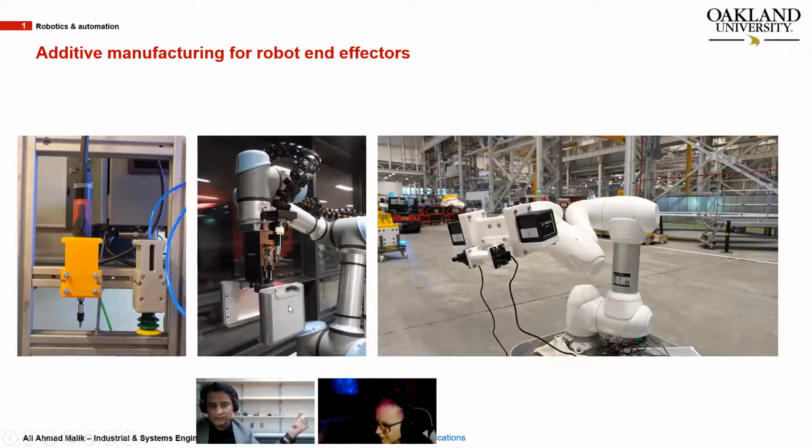For example, here it is attached to a gripper, or these tools are also developed with 3D printing and the robot can pick them with its fingers. In the case of this robot, it needed to pick or hold some lasers, so this whole component is developed with 3D printing. If we had tried to develop this by machining out of aluminum, it could have become more expensive and would take much more time.